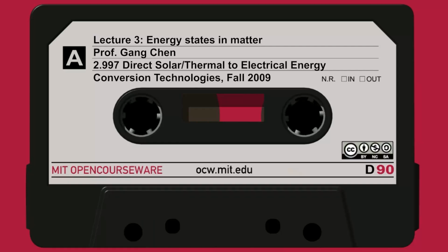I can start by reviewing what we talked about in the last lecture. We introduced thermoelectric effects, including Seebeck effects. When we have a temperature difference, a voltage is generated. That's the phenomenon, right? And then we gave a microscopic picture of what happens. This is really the diffusion of charge. On one side of the path, the charge diffuses to the other side.